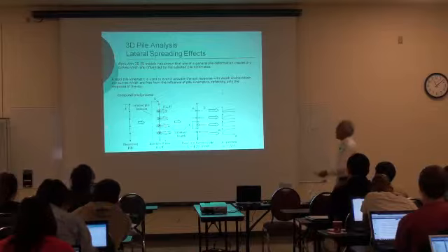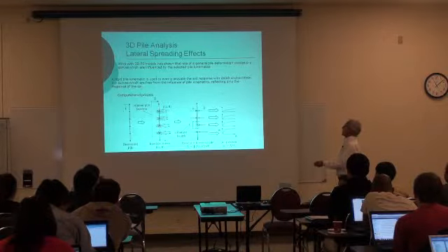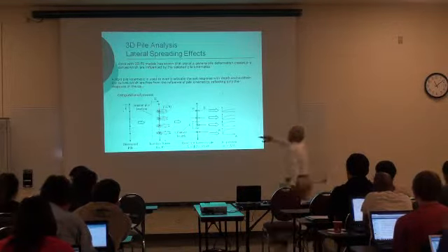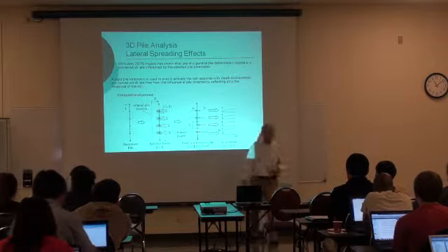So what you do, in general, is get the contact forces. From the contact forces, you get the force that corresponds to each displacement. And if you have different displacements, you can get the forces. You can reproduce PY curves at different locations and for different kinematics.